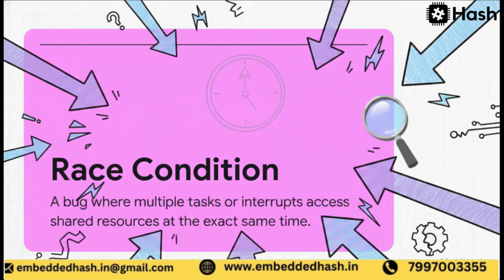Then we have race conditions. These are incredibly common, especially if you're running a real-time operating system or RTOS. This happens when multiple tasks, or maybe an interrupt and a background loop, compete to access the same shared data or hardware resource at the exact same time. The truly infuriating thing about race conditions is that they usually only make the system fail under very specific, nearly impossible to replicate timing scenarios. Your system might run perfectly 99% of the time and then just inexplicably crash on a Tuesday afternoon.